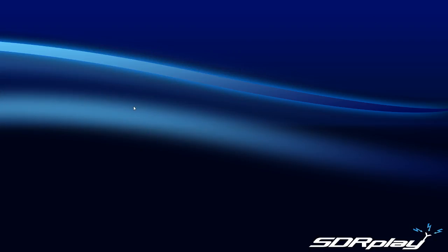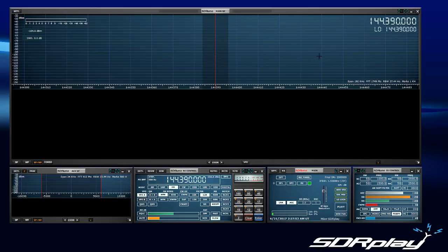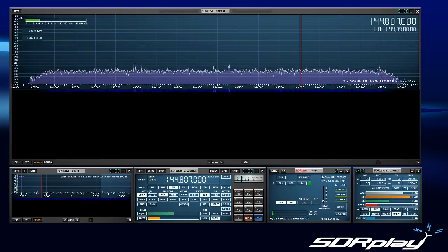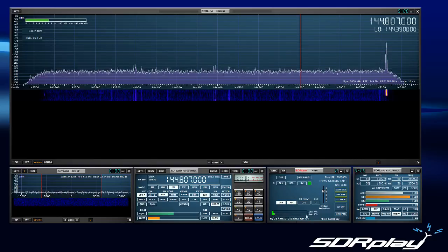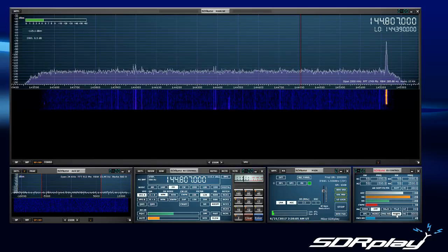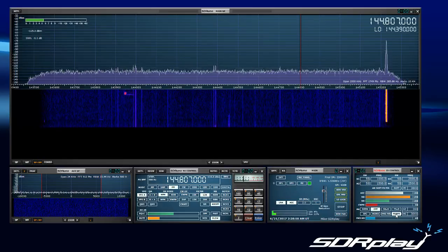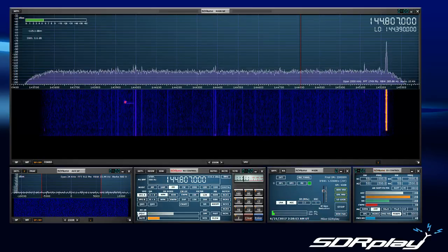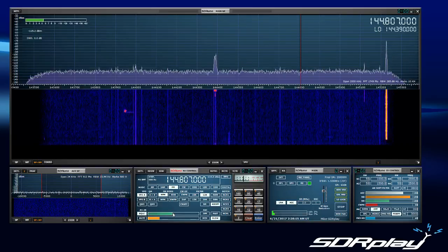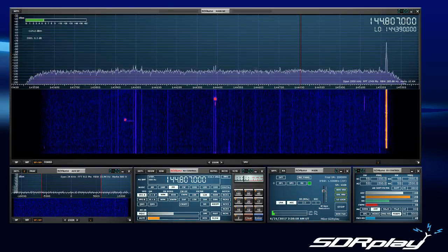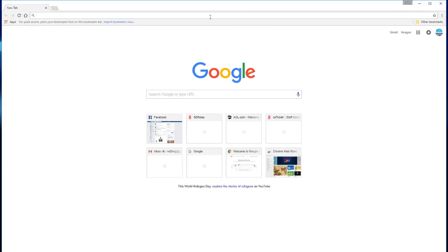Alright, now let's launch SDRuno. We're going to give ourselves some separation between the tune and the LO. The mode is narrow FM, 12K. I have the filter enabled, otherwise it's just not going to sound right. I figured you guys don't want to hear static. You can also enable the squelch, and you can use that almost like a gate. And let's pull up that document again.